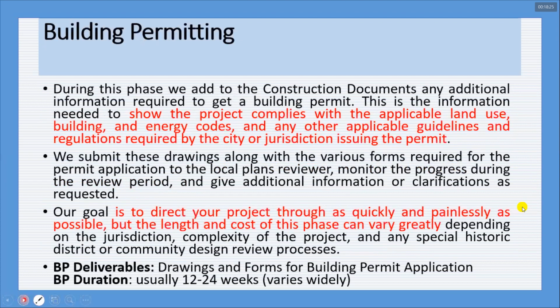The next process is regarding building permitting. Building permitting is just like asking for the license to build a building on a particular site. Might be regarding land uses. Land uses are again the zoning scheme on your project. Then energy codes, for example, the site has bylaws that you have to produce some energy from the constructed building in the form of solar panels or any other form. Or you have to conserve water by adding any conservation technique for water reservation.